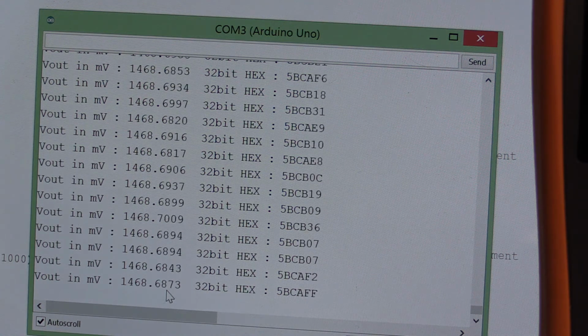So in this case, if we're wanting to set a power supply up and control it, you're talking 1.1%, 0.1, 0.01. You'd probably be able to get 0.01% accuracy, but definitely, that's without any calibration and software compensation for the readings.